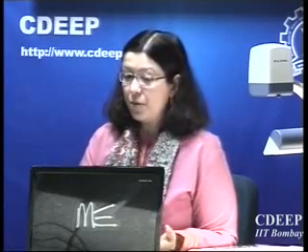As I said, the architecture is nothing that I should teach you. It's very easy to learn, and you may even know it before. What is important right from the beginning? If I have a resistive network which generates reference values, and a set of comparators which compare the input signal with reference values, what will be the effect of comparator offset? What will be the effect of variation in this resistive network? Of course, a flash ADC, if it is a large ADC, has its own problem. But right now, we don't look at it.